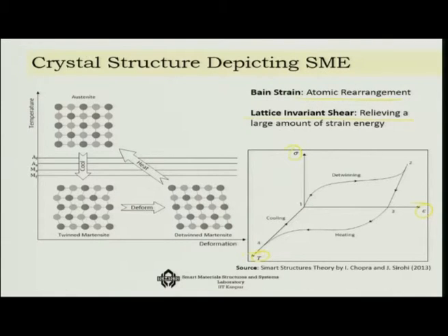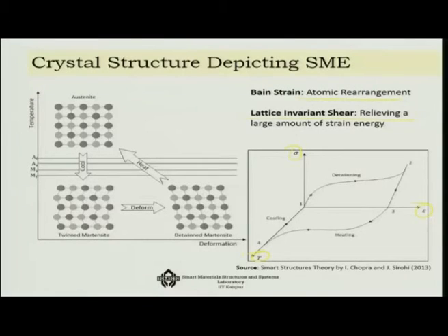temperature. So far for all the materials you have only seen the stress strain behavior, but now temperature has also come into the picture. So let us say I have taken a material which is at its original point number 1, okay, and then I am loading it. As I am loading from twined martensite, so this is the twined martensite state. As I am loading, I am detwining it, and then it is coming completely detwined phase.